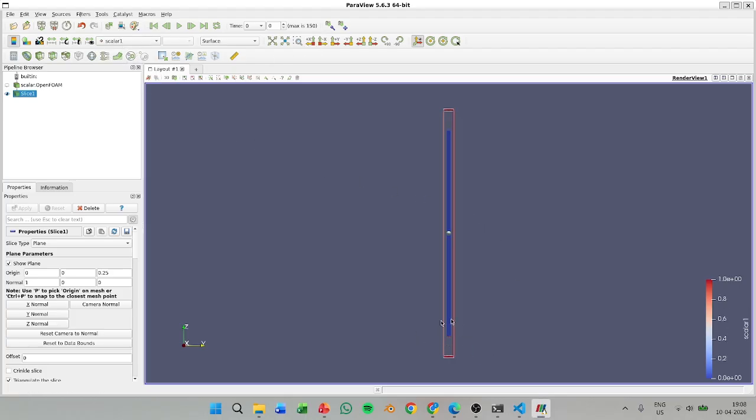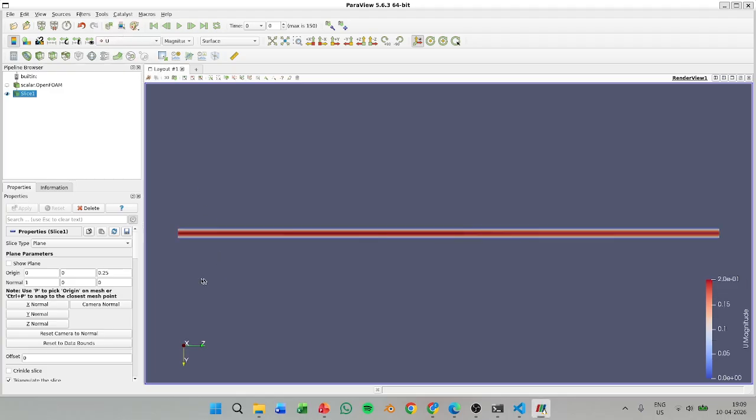So it's coming from this end. Okay. So this is your inlet part. So we'll rotate it this way. Yeah. So this is your geometry. So if you see for velocity, you have a fully developed flow because we already ran the whole simulation previously for flow. That's why you won't see any disturbances in the flow field itself. Okay. So you see this is the flow. Once you run it up to 150 seconds, there is no change in the flow itself because it's completely developed. It is set properly. Okay.